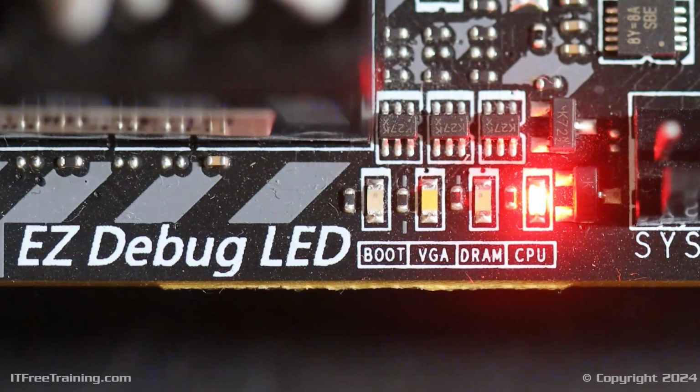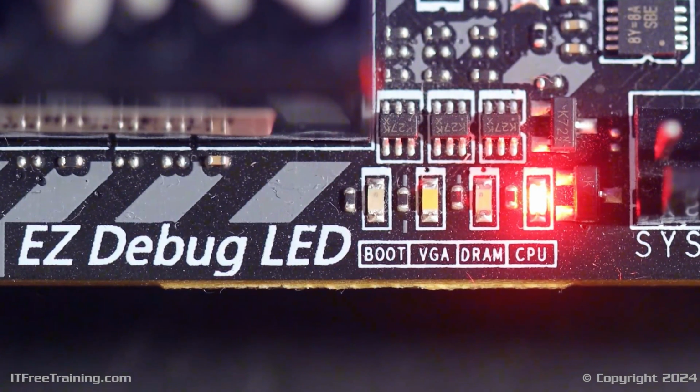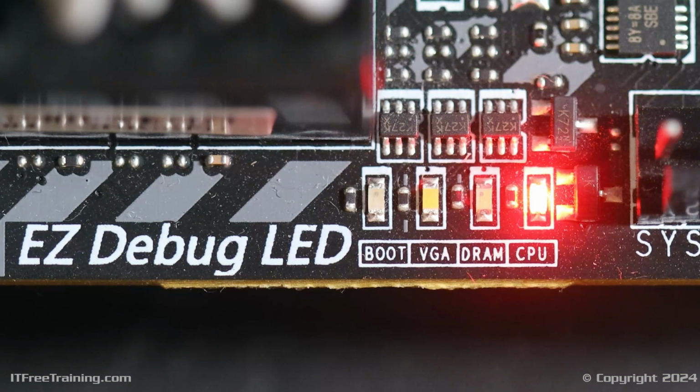On this computer, notice that there is an Easy Debug LED section. The lights will indicate where the problem was detected. If you are having problems, have a look around the motherboard for any lights that come on, even if you don't have a post-LCD screen. You may have Easy Debug LEDs, which may help you work out what the problem is.